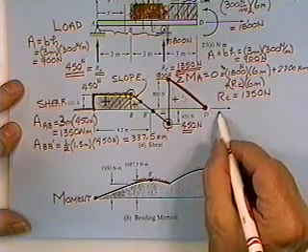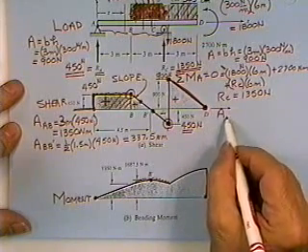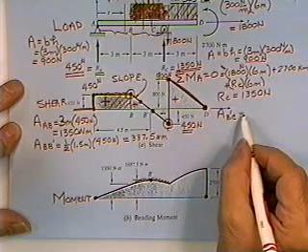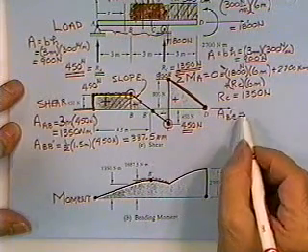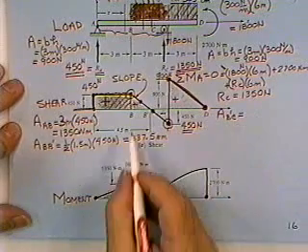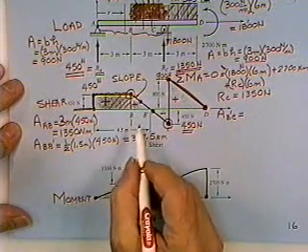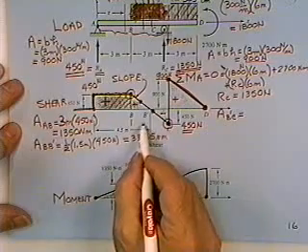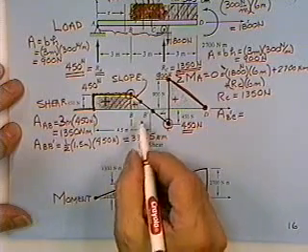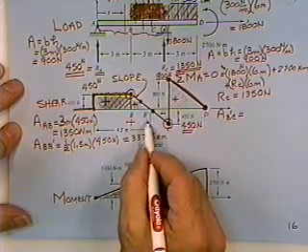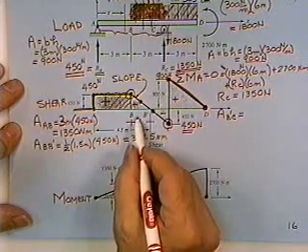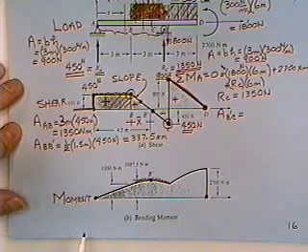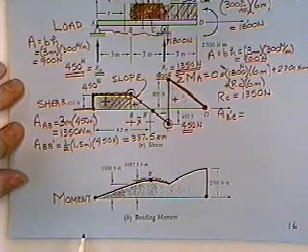Then I calculate the area for piece B prime C. Ooh, I cheated. Because the thing said this is 4.5 meters across there, it was pretty easy to figure out that was 1.5 meters. But that's not easy to do. That's X bar. That was one of the rules we laid out a minute ago.